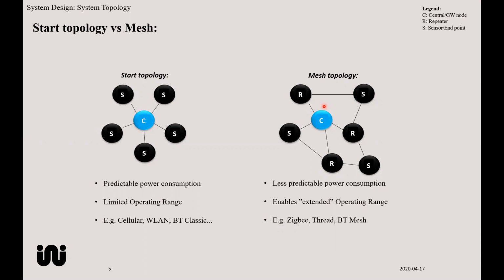In any case, the router needs to be running more or less continuously in order to receive messages to judge whether it should route it onward or not. And therefore, mesh topology is not that well suited for IoT systems if you have very, very low power sensors. Then you could argue that you could have a very low power sensor in the mesh network, and the routers might be powered by mains or larger batteries, of course.